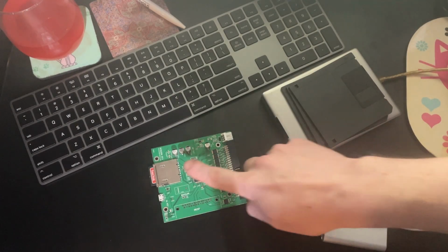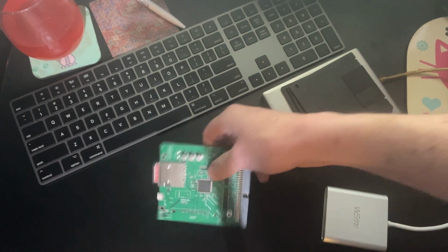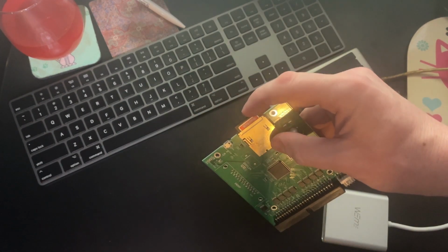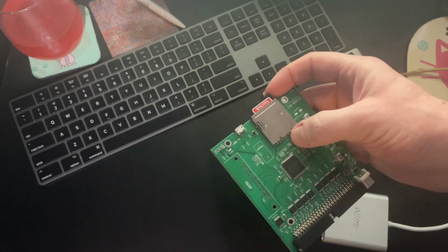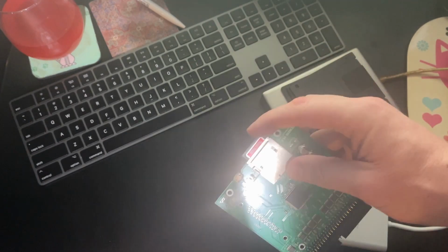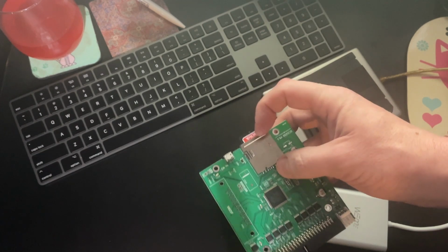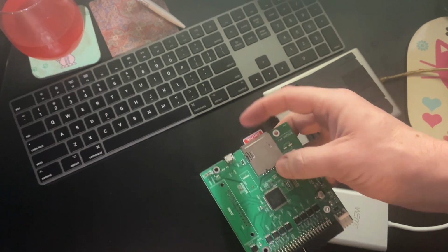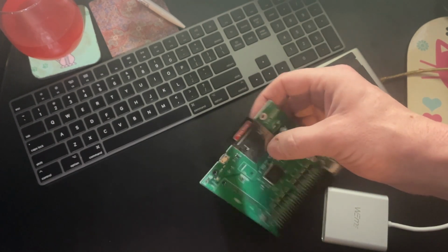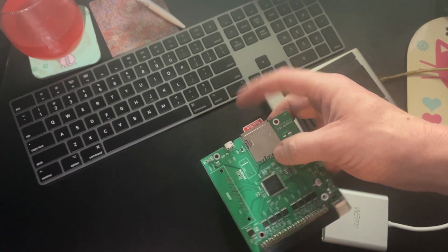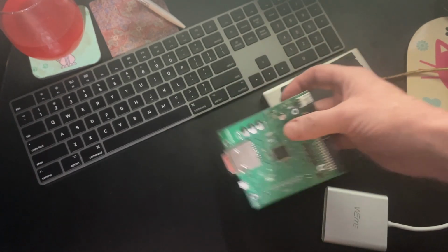Alright, things you need: a SCSI 2SD device with an SD card. The size doesn't really matter, but the pre-made images come in 2GB sizes, so either get a 2GB card or not much more. If you don't want to waste the rest of the space, you can set them up as additional storage partitions if you like.